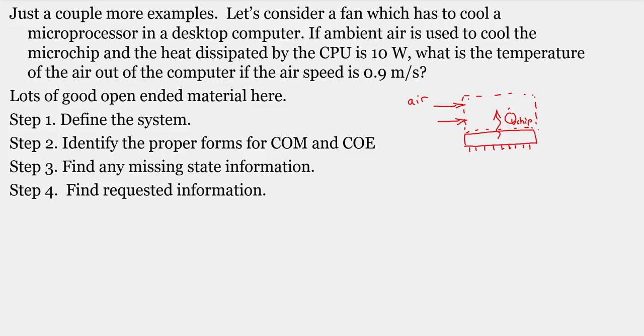Well, you know that to a certain extent, imagine if you have a little box heater, a little flat film heater. A certain area above that heater, you're not going to feel the heat transfer. That heat transfer isn't going to be observable in that air. So that's probably your upper bound, where the temperature is unaffected, which is where the upper bound of the control volume would be. And then what's the width? Well, that'd nominally be the width of the film, or the width, in this case, of the microprocessor.